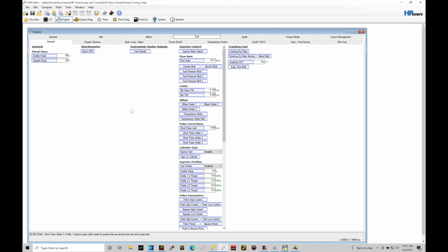There's all kinds of options on the market, or a meth injection kit where we're spraying the additional meth in and the meth controller brain is controlling when that additional meth and how much meth is coming into the engine. So the engine control module here doesn't understand what's going on externally. Those are external fuel sourcing devices that don't tie into the programming language here. How do we get around the situation so we don't run rich and we don't skew our fuel and airflow modeling relationship?